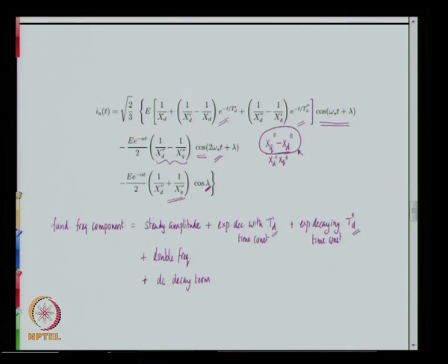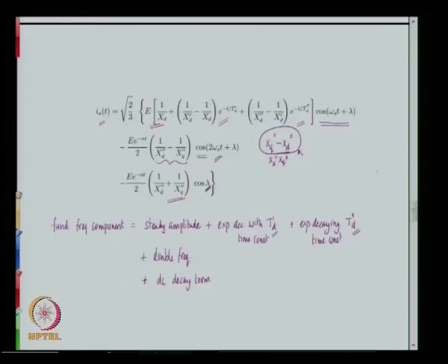Finally what we will be left with is only the steady state term, and therefore if we find out the steady state amplitude of the resulting waveform of Ia subjected to a 3 phase short at the alternator stator, then from the steady state amplitude it should be feasible to get the value of Xd.